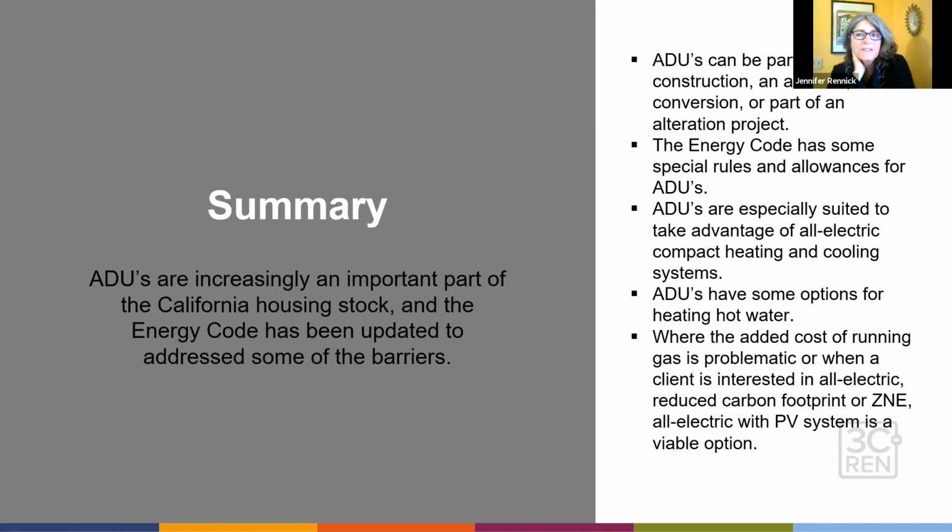Yeah, that's a good question. So is the ADU new construction standalone? I mean, if it's standalone new construction, I think you're going to be required to have a 200 amp panel no matter what. It is a standalone garage conversion. It's an existing structure from the 40s.